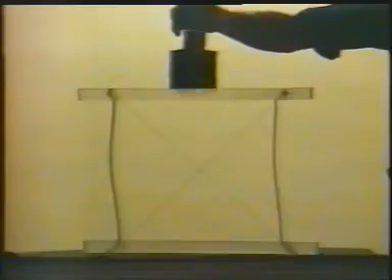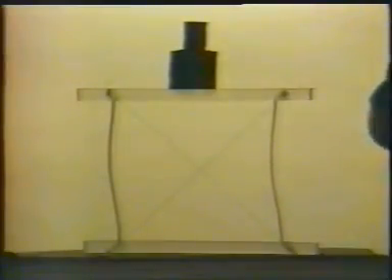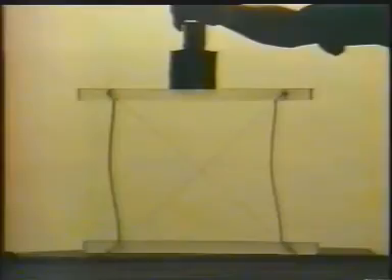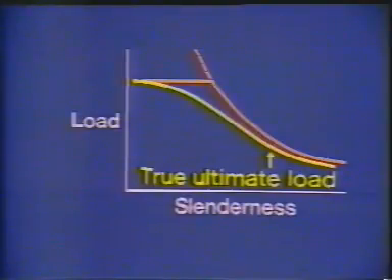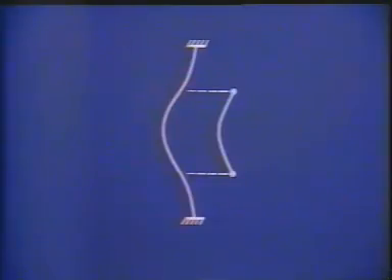The lateral deflection is no longer a single half wave, but has zero slope at the fixed ends. The effective column length will, in this case, be 1/2 the actual column length, and the column will fail at up to 4 times the collapse load if it fails elastically. The effective column length is used with the design curve to calculate ultimate capacity. The column section will behave exactly as if it were a simply supported section with a length equal to the effective length.